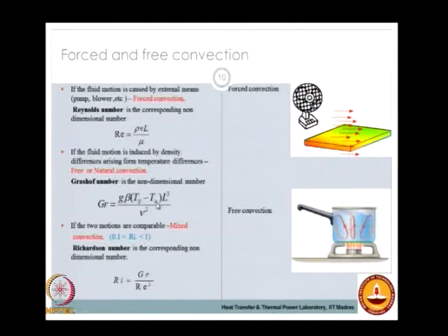In the case of Reynolds number we use the ratio of inertial force to the viscous force. Here the inertia is replaced by the strength of the buoyancy force, which is related to the temperature difference between the hot side and the cold side. Typically you can see free convection when you boil a liquid. You do not boil it too much, just during the initial stages of boiling, when you apply lower heat fluxes, you can find convection currents rising from the heated surface at the bottom towards the cold surface outside. These are small currents which are set up and which can improve the heat